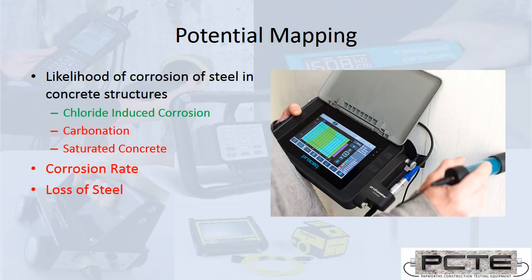Okay, so if we look at a physical layout where we've color-coded regions of different half-cell potentials, we can look for a couple of different approaches to locate areas of corroding reinforcement. We can try and find hotspots where the corrosion potential changes markedly compared to the rest of the structure. Or we can actually do some statistical analysis upon large data sets. It's possible to look at the distribution of half-cell potential voltage values for the whole structure and pick out those that are likely due to non-corroding reinforcement where a measurement's been taken, and also to measure regions where the reinforcing is corroding. These two numeric values, the distribution of them can be used to statistically